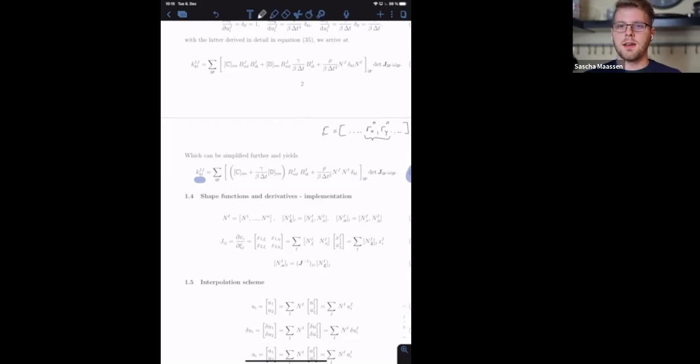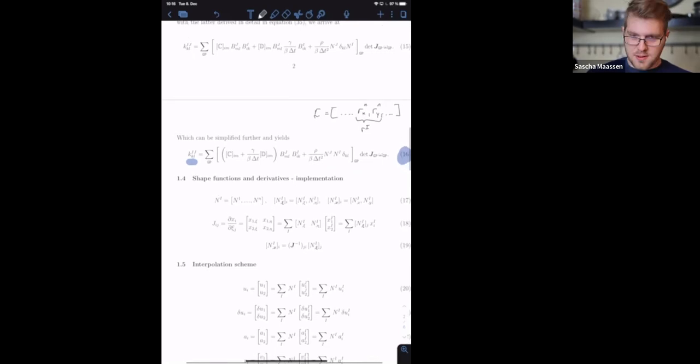Here, X and Y, meaning this is the right-hand side equation for the displacement in X direction, while Y is of course in Y direction. You can imagine, as discussed last time, a potential third degree of freedom per node being the temperature will lead to, for example, R theta here, and the superscript N will of course be related to the node number, and therefore this is kind of Ri here, which we will program in a loop structure, but I'm pretty sure you remember that from all the other courses.